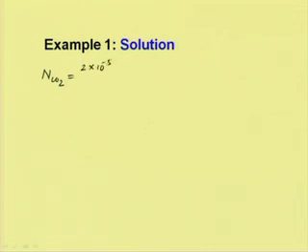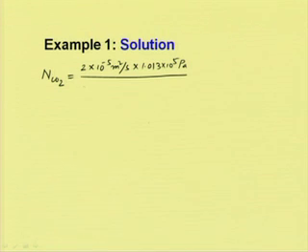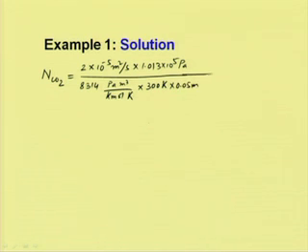into 10 to the power minus 5 meter square per second, and then the total pressure 1.013 into 10 to the power 5 pascal divided by R, 8314 pascal meter cube per k mole Kelvin, into 300 Kelvin, the distance 0.05 meter, into the log mean partial pressure of component B, 88590 pascal, into 20,000, partial pressure of component A at point 1, minus 5000 pascal.